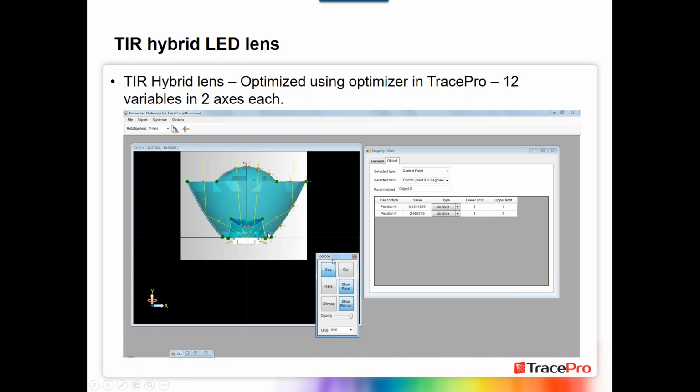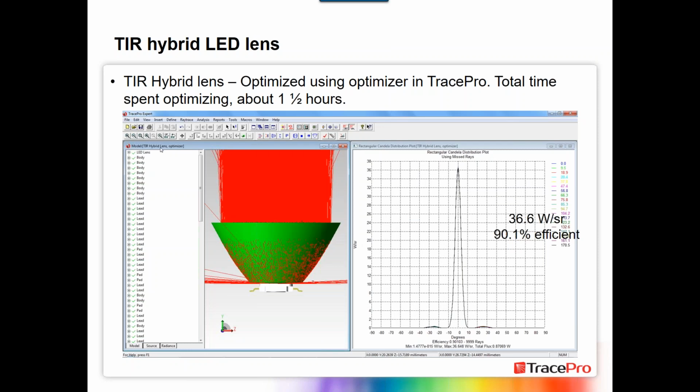In our optimization utility, there's also the ability to draw rays. So here's some rays sketched from the source, showing their path through the system. And if I was to go in and actually move these points, the ray trace in here will update in real time. So we can use that as an initial design tool to get our starting point close to where we want to be.